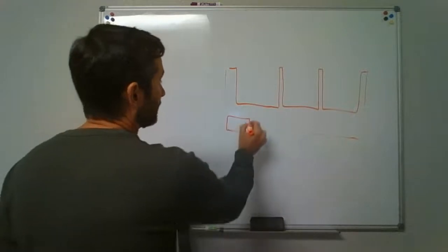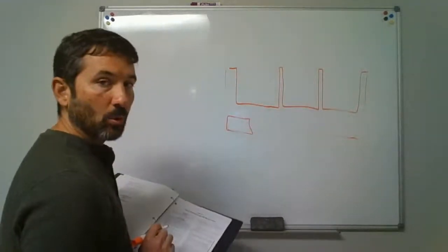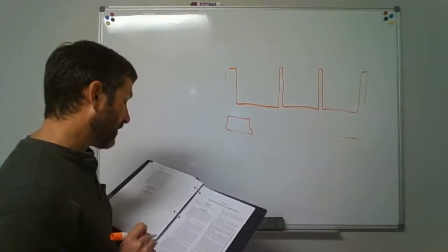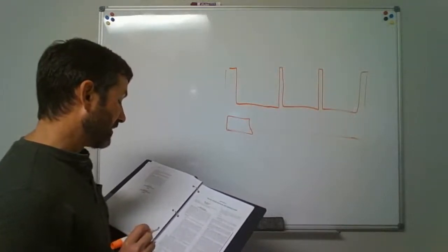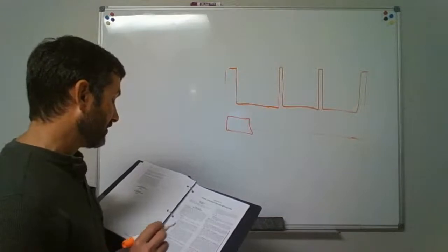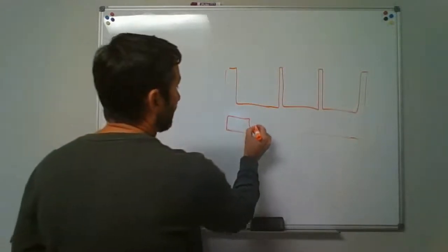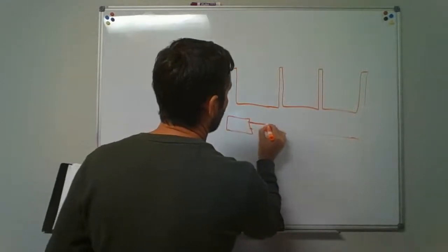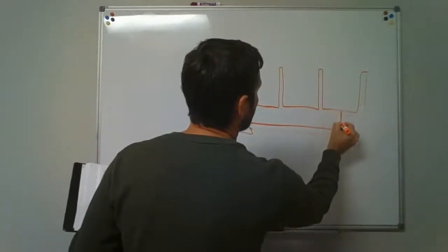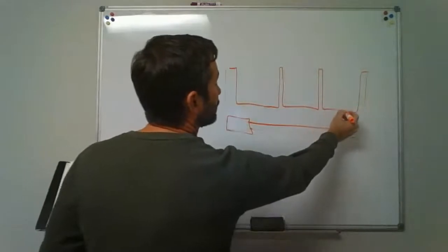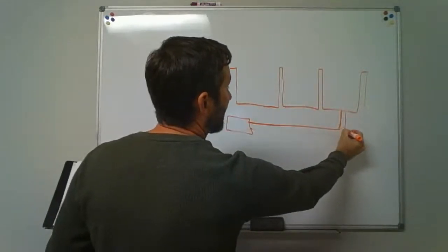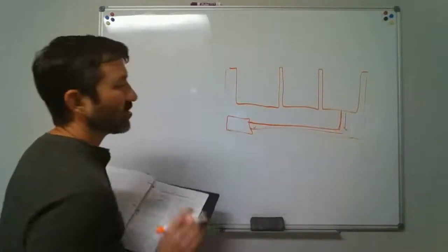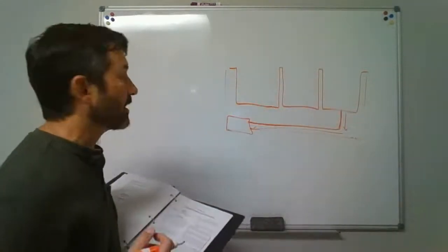So a vertical drop of not more than 30 inches, and the developed length of the waste pipe from the most upstream fixture outlet to the inlet of the interceptor does not exceed 60. So if we have an inlet of the interceptor here, okay, well, let's take that inlet, let's run it over. As long as from the most upstream one, the total developed length, so you've got to measure it down, and then you've got to measure over. You add those two together, and as long as that's not more than 60 inches away, you're okay.